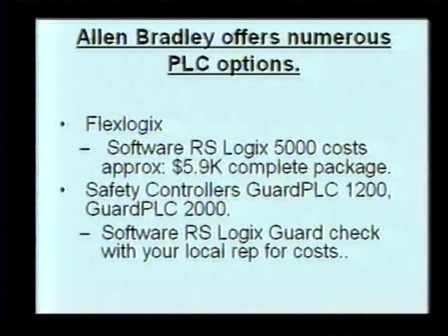And it's a whole unique way of programming. It's a whole unique way of understanding how the safety system works, and it's not recommended. Anytime you run into a safety system, it's probably a better idea to use relay logic or different SIL-rated relays or PLCs. So in this example, a Guard PLC is SIL level 3. A ControlLogix PLC with the special software is SIL level 2. And all the other ones are SIL level 0s. They're not to be used for safety.